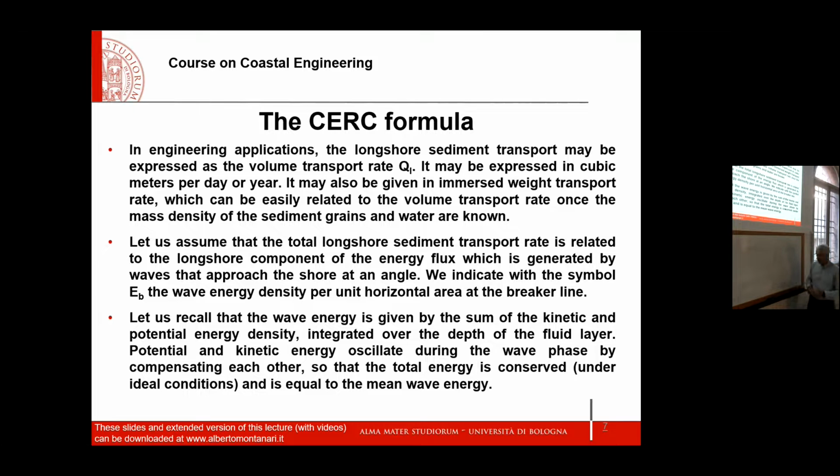Let me call with S the coordinate, the spatial coordinate along the coastline. So I take a delta of this length of coastline, which must be reduced. It cannot be very large. And then I estimate here the volume of sand that is eroded. Once I know the volume, let's suppose that it's a minus volume, so something that is subtracted, I can predict that next time step, the beach will move here. How? We will see. Okay? And if in the next delta I have a plus, it means that this volume that was eroded here is displaced here.